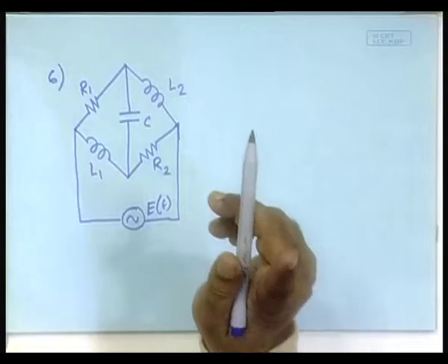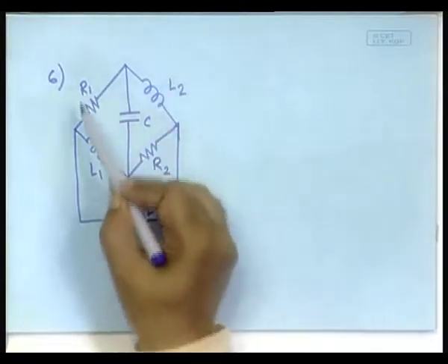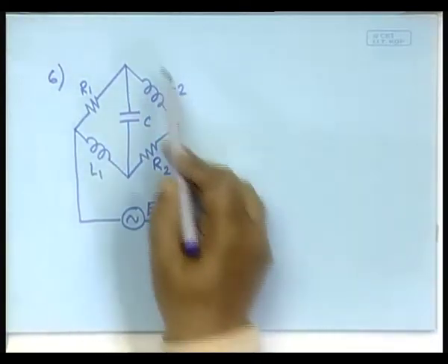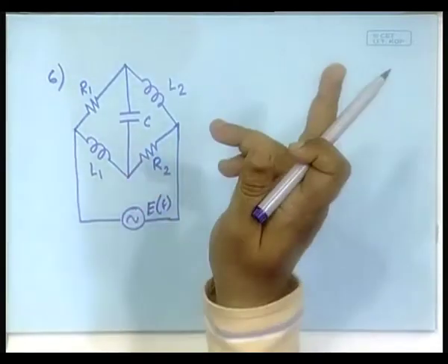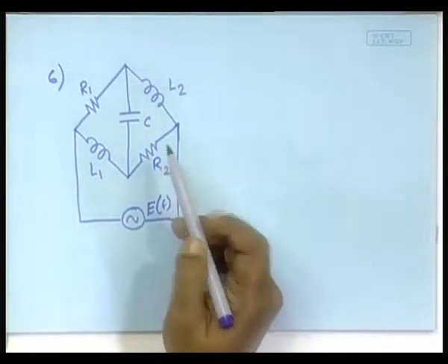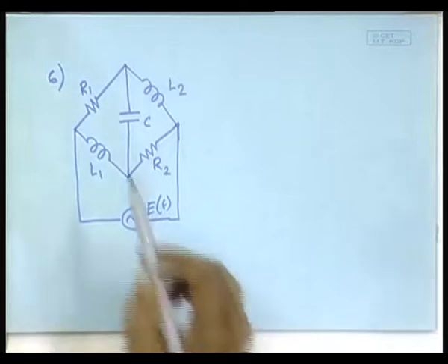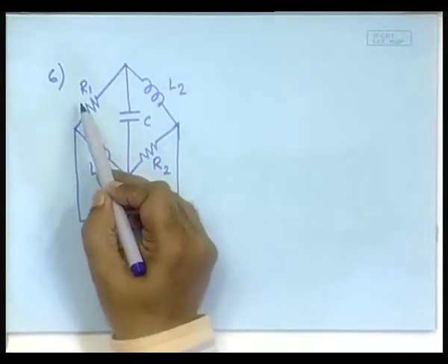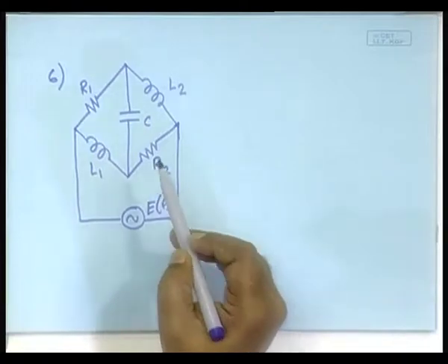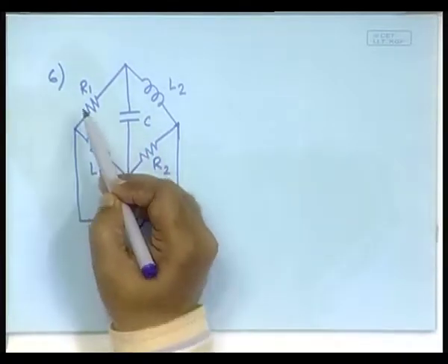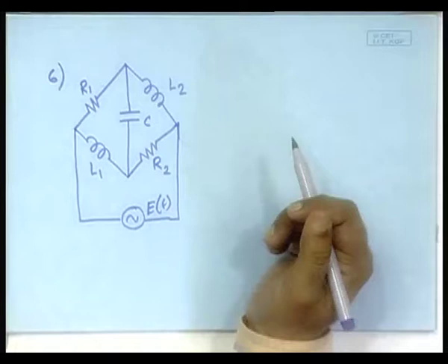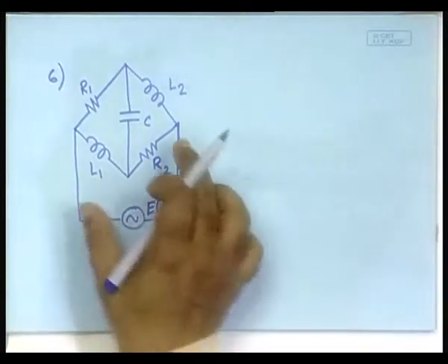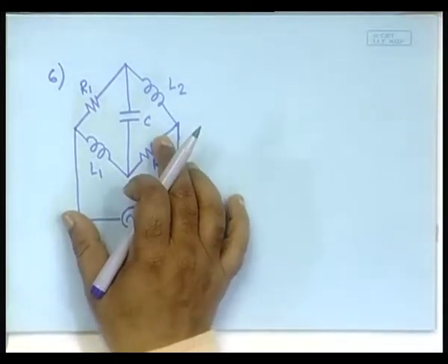So, do you remember what algebraic loop is? If you write the bond graph, how to write the bond graph of a system like this I have already shown, right. But when you want to put the causality, you will find that these two will become difficult to causal. You have to assume a causality here, then this will be causal, or you have to assume a causality here, then this will be causal, and such a system will be giving rise to a differential causality. So, obtain the differential equations for this system.